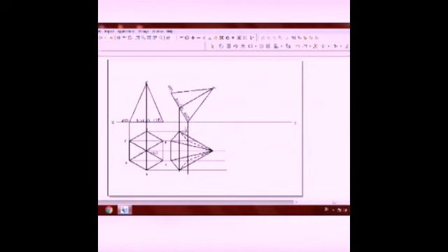Trimming is a very important activity. Do the trimming to clean up the area. All the unwanted lines are to be trimmed off, and only required lines are to be there. If very small portions are to be trimmed off, the best thing is to zoom in and do it. Again, the Zoom Area command will make it clear. Zoom that particular area and see the lines that you have to trim. Go to the trim command, and now you can trim such small lines.